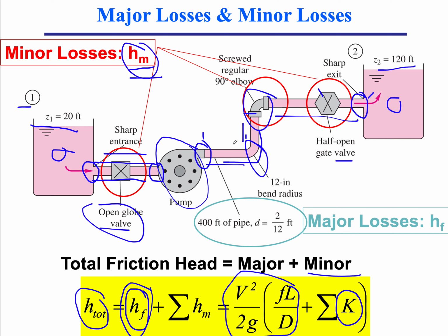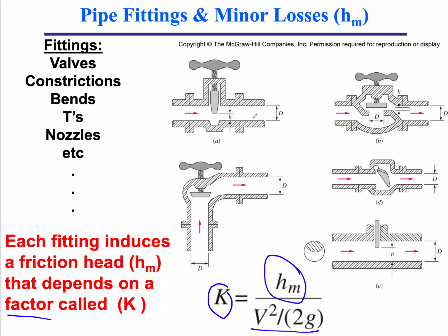And if I'm having the same diameter pipe that goes with the elbow, it'll be the same velocity as comes in. But you'll have to look carefully at this velocity on each plot associated with one of those valves. So you can have different types of valves, fully open, half open, partially open, and so on. And each one would have its own K, depending on the level of opening.